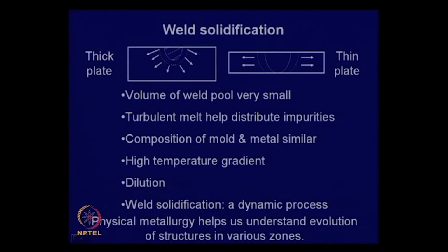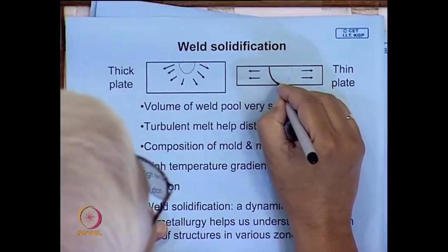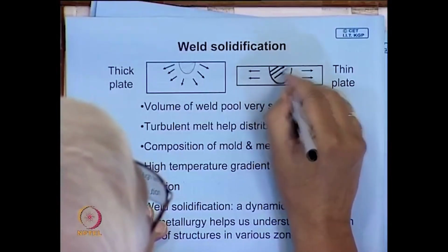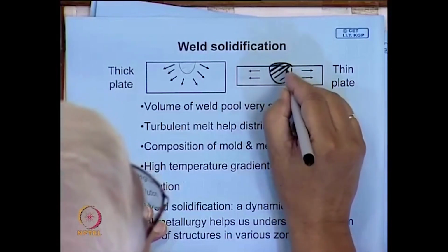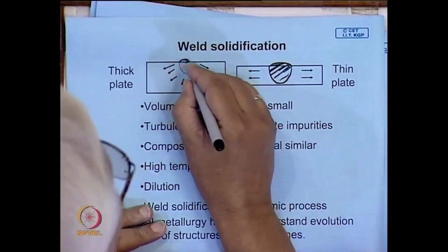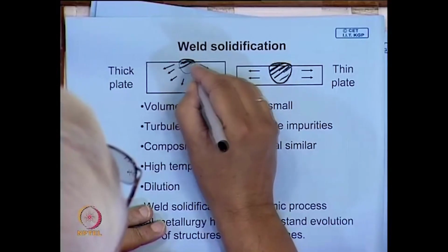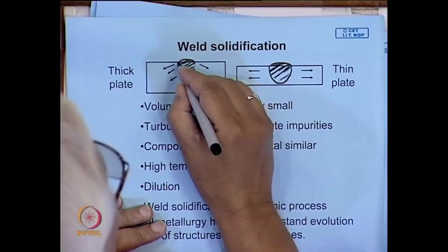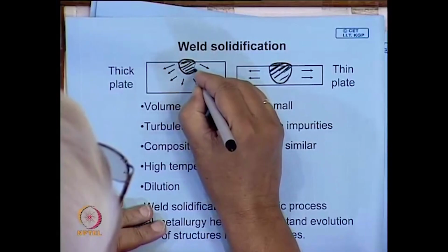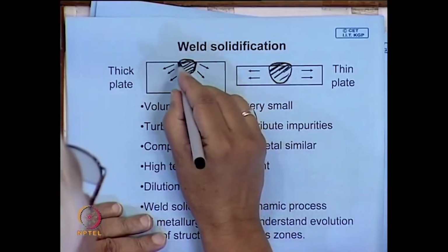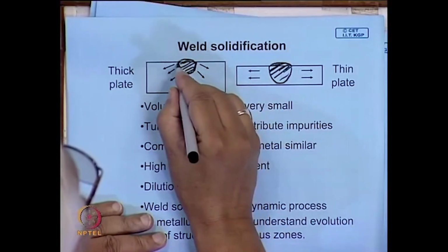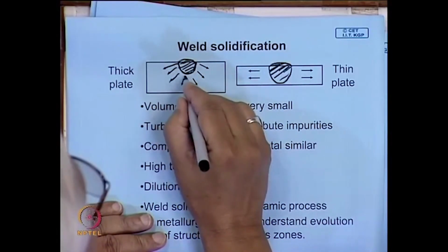We will just look at this here. This is the molten pool, and in fact this will be slightly raised. Here also this is the molten pool. A thin layer beneath it of solid will also melt, and in this particular case, beyond this fusion zone, heat can flow in all possible directions.